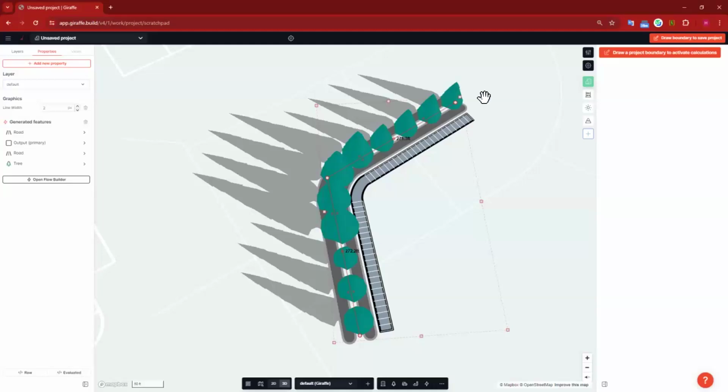So you're kind of thinking, okay, I want to have 2 different roads. That means I have to output 2 lines and apply the road usage to those lines. I want to have a row of perpendicular parking spaces. That means I need to create another geometry that is 18 feet deep to accommodate those parking spaces. And then I need to apply the parking space transform to draw the actual spaces. So it's all just using the logic of if you were going to draw it manually, but instead of drawing it manually, you're just inputting those numbers into the algorithm and then it draws it for you.